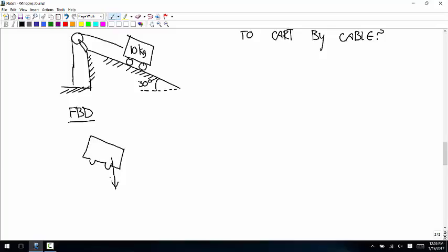So there's a weight force of 10 times 9.81, so 98.1 newtons, straight down. Then there's a pushing contact from the incline onto the wheels, and that's frictionless, so we know that the direction is perpendicular to the incline toward the chosen body. All right, that is N. And the cable force is parallel to the cable away from the chosen body, so this way.